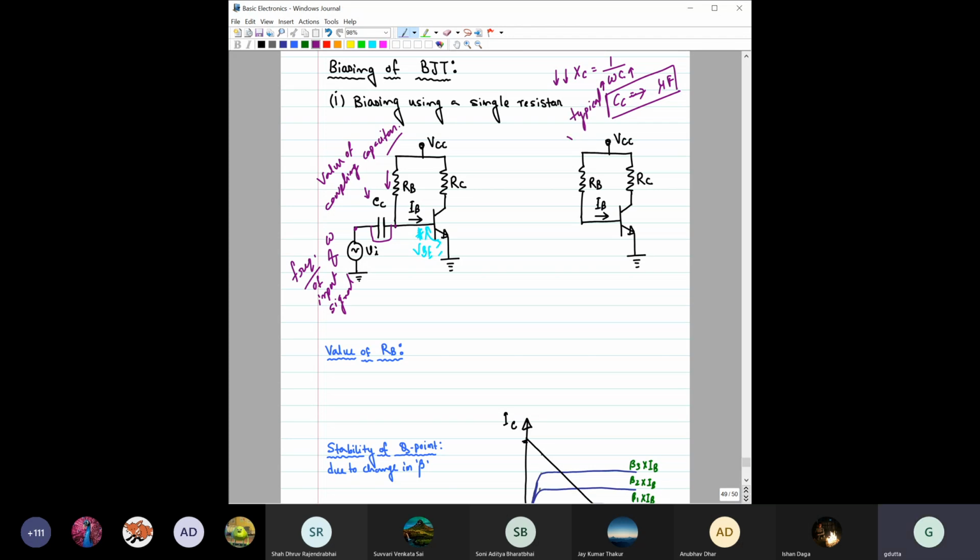These microfarad capacitances are very high capacitances. So you understand how you can design this amplifier circuit. But here, you see, we do not need that VBB anymore, right? We have replaced VBB by using this RB only.